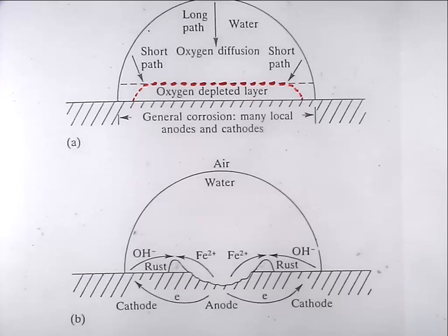So there's something, in this case overlap of some plates, that gives you a pre-existing structure. And so it's really very similar to pitting, but the initiation time is smaller because you've already got the crevice geometry, and you find in a whole lot of situations